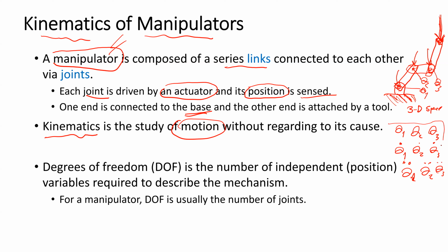And these are in the joint space. We also sometimes talk about the position in the Cartesian space. It seems like in our application, we mainly want to control the position, the velocity, and the acceleration of the robot in the Cartesian space. But what we can exactly do on the robot is to control the joint variables: the joint position, the joint velocity, and the acceleration.